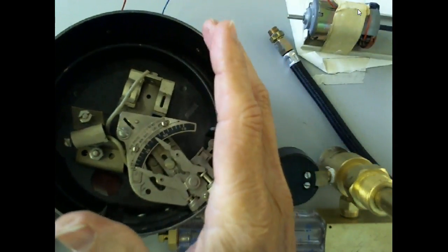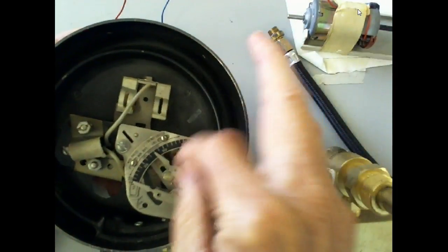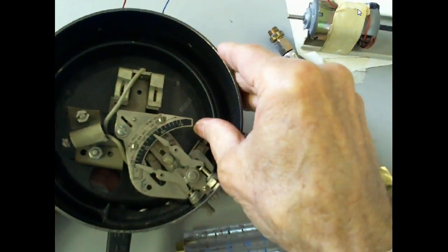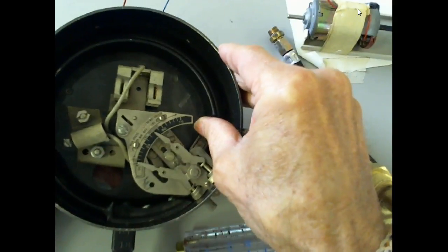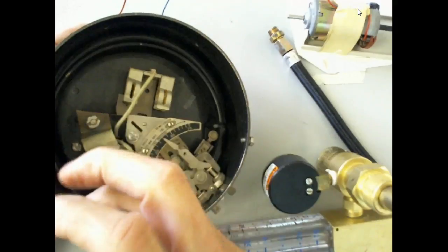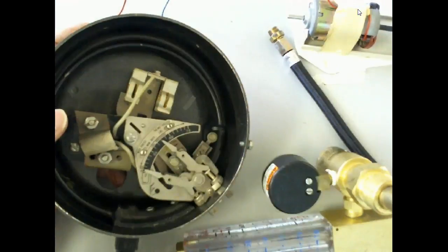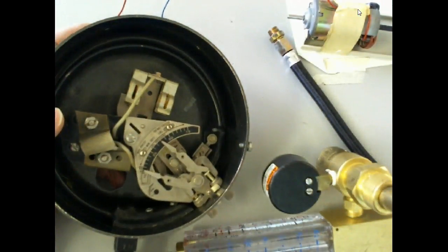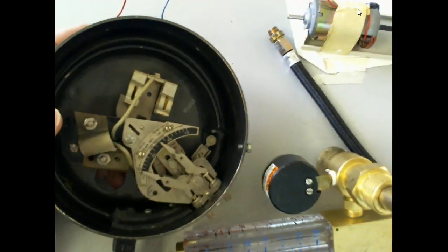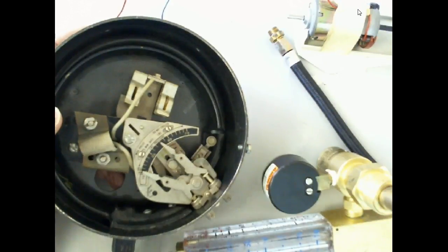Now, of course, here we have this would be digital, right? You understand? But we could come up here and replace this wiper down here. This actually moves proportional. Y'all can see it's moving proportional to the temperature. We could hook this up to an LVDT. We could hook it up to a potentiometer. We could hook it up to a lot of different things. So we can use this Bourdon tube as a sensing element. And then our transducer is either going to convert that over to electrical, and then we have our signal that's going to turn it into either digital or what.